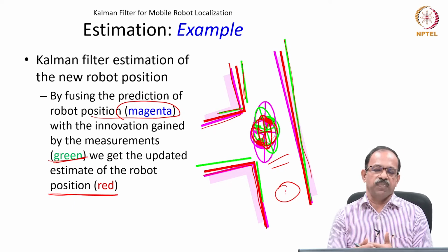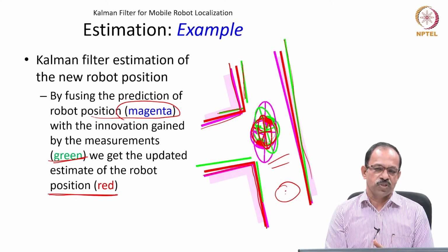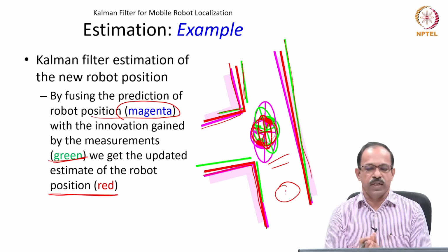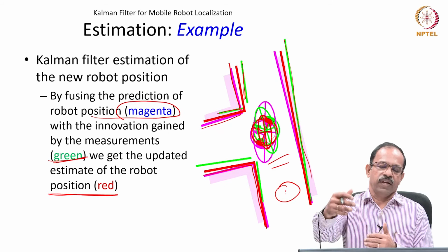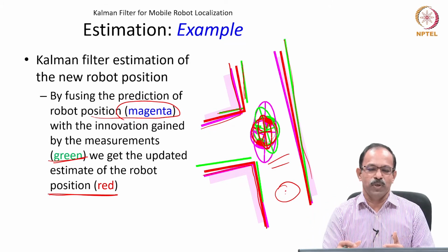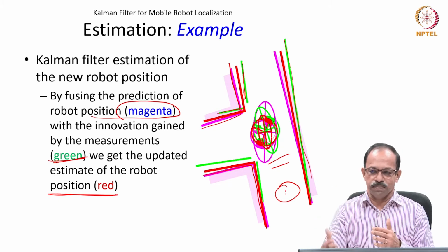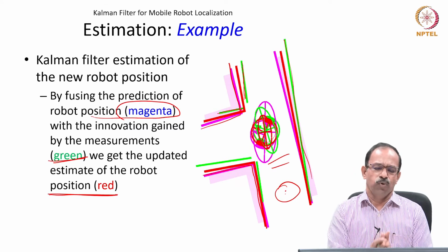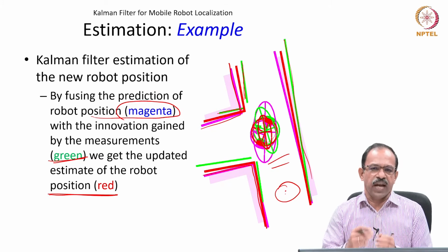So, this is the step that the robot will be taking at every movement. As the robot moves, it will calculate using the odometry, and then it will update it using the sensor, and again it will move and keep on doing this. So, this is why the robot needs a bit of computation as it has to move. It has to observe, then identify the edges or features, do the matching, and then recalculate its position and correct its position, and then it moves forward.